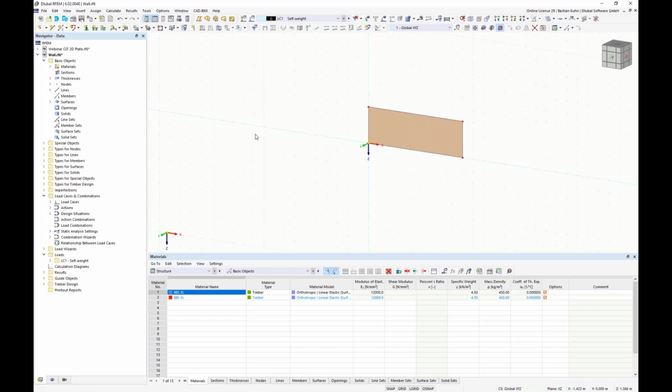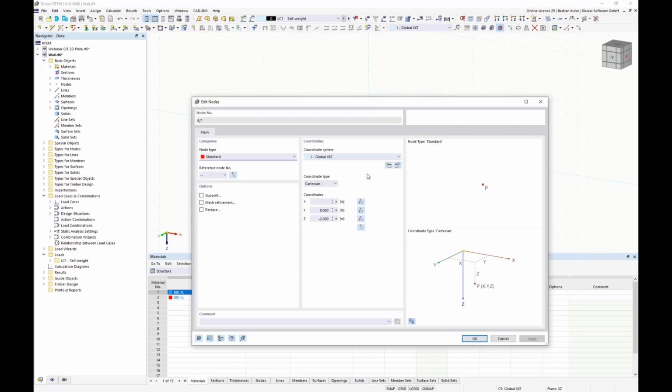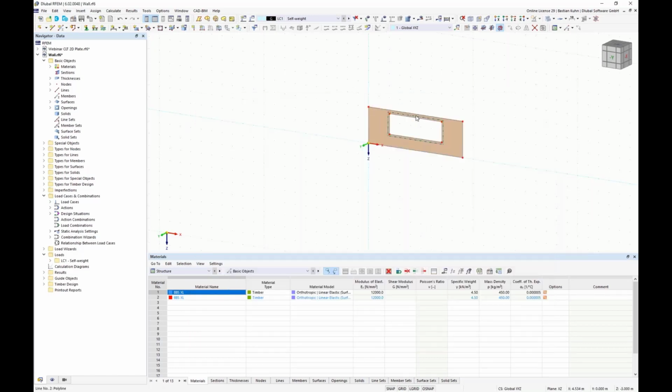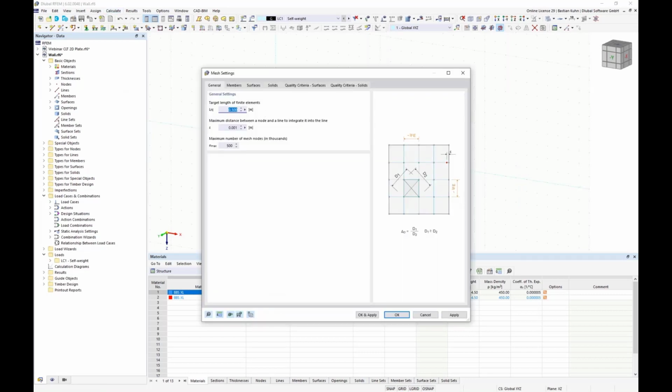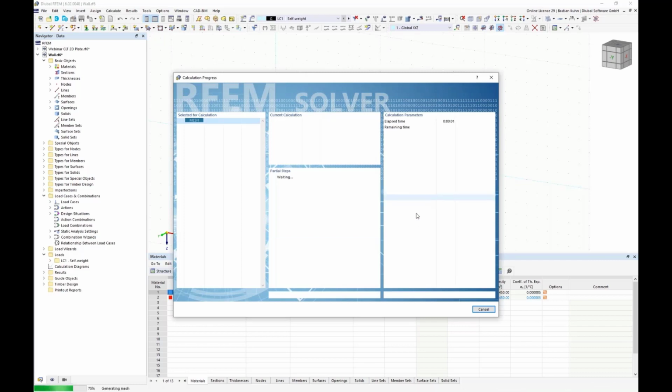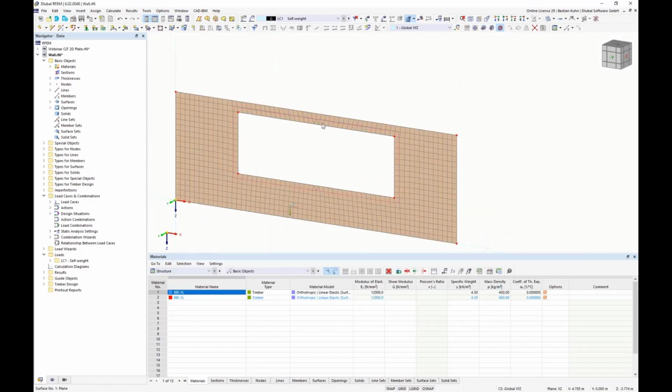So okay, we make it a wall, give it a little opening, assigned here by this, just to have it symmetric. And in order to see something there with the shear problematic, because that's the only reason I'm showing you this example here, we make it quite narrow here on the top. And because it is this kind of narrow, I have to refine my FE mesh in order to have at least 2 elements over the height of this little spandrel in here.